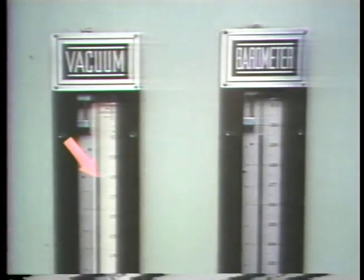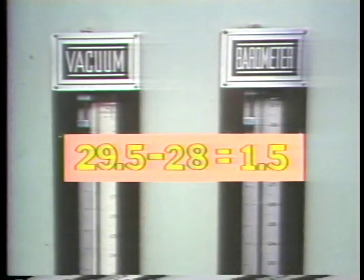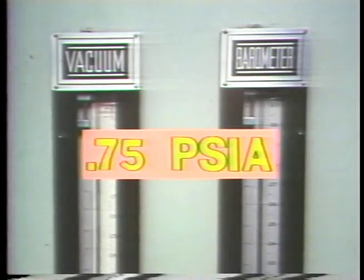In this case, the condenser manometer is reading 28, while the barometer is reading 29.5. 29.5 minus 28 equals 1.5. The back pressure is 1.5 inches of mercury. If you want to know how many psia this is, you would multiply it by 0.5 to get an approximate answer. The back pressure is approximately 1.5 inches of mercury, or 0.75 psia.